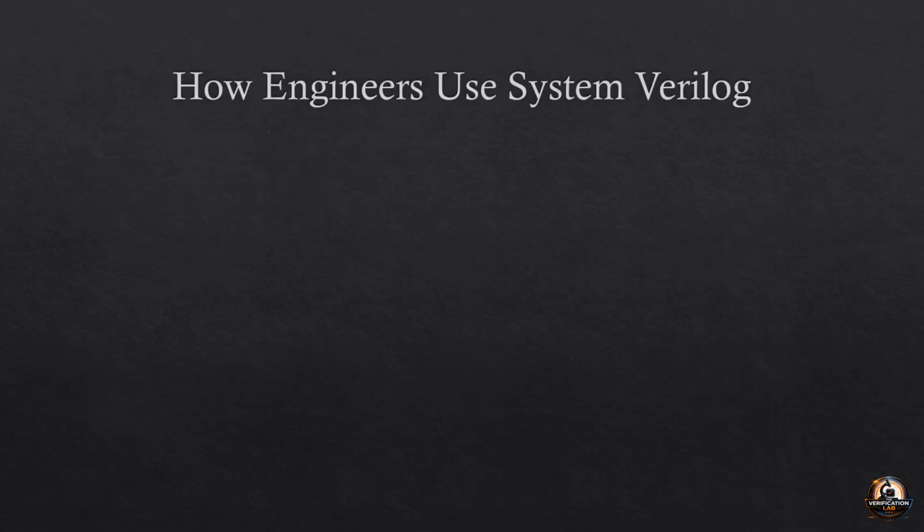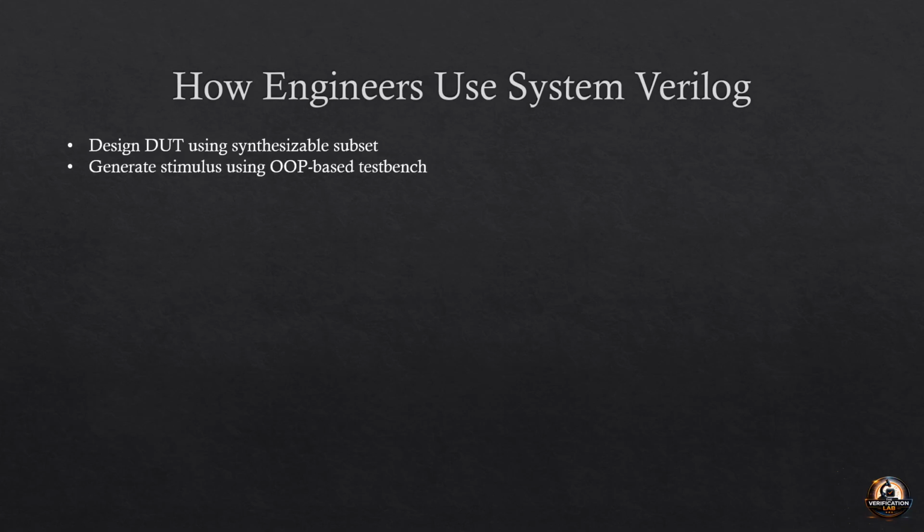How do engineers use SystemVerilog? In a typical workflow, engineers design the DUT using RTL constructs, the synthesizable subset, that can be translated into actual hardware. They create testbenches using object-oriented concepts that solve the problem of reusable and modular testbenches.